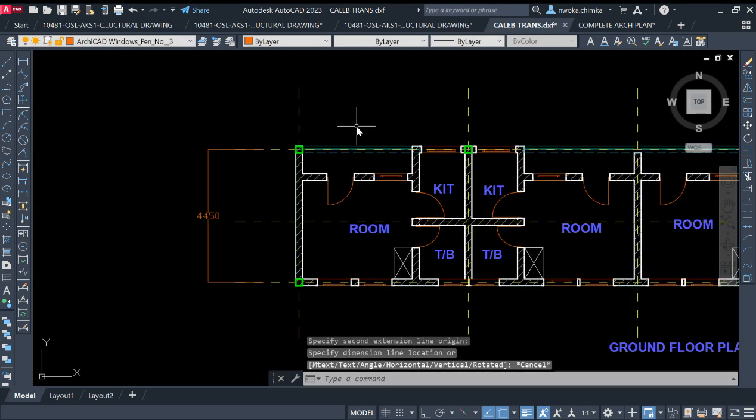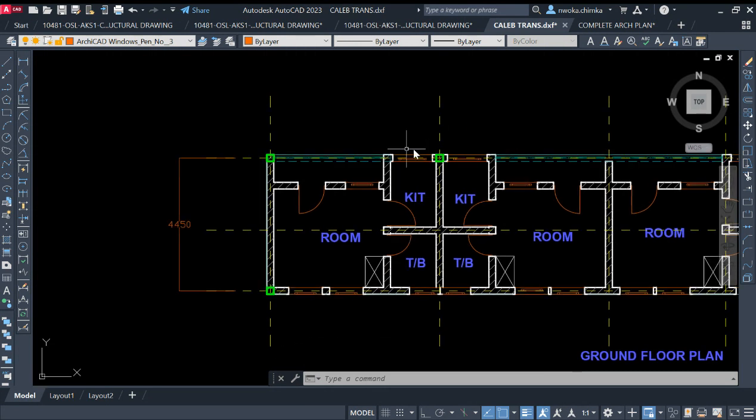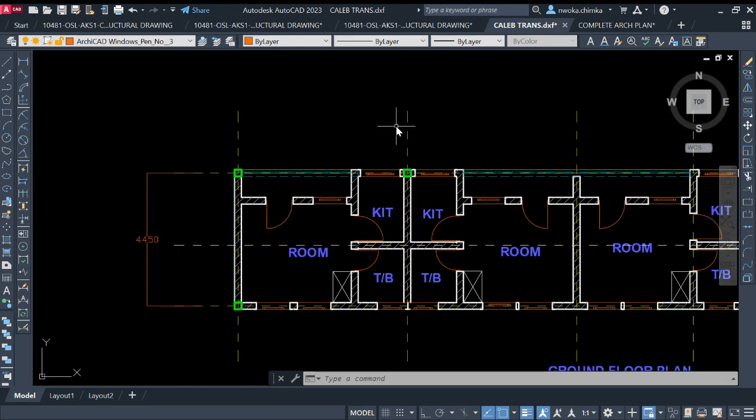So I'll say that for a beginner in the design world as a structural or civil engineer, make sure that your column distance for a residential building is less than 6 meters, at most 6 meters. But when you are strong in the design world, you can begin to go up to 8 meters, 10 meters.